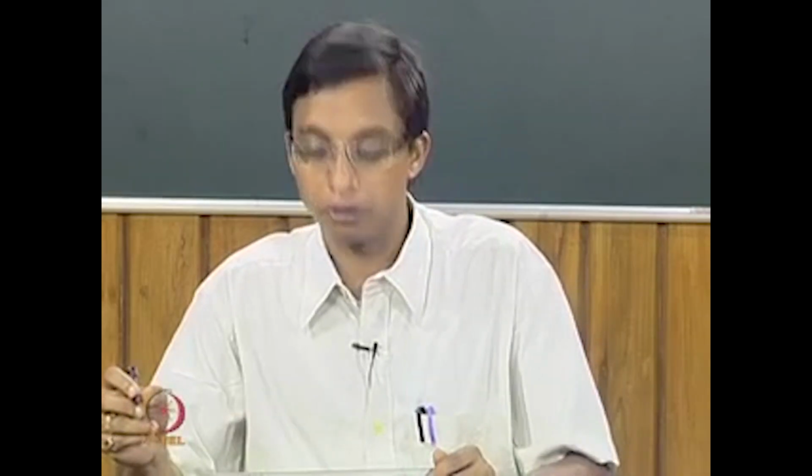I am just showing you how you incorporate the sequent depth ratio in the above efficiency relationship E2 by E1, and correspondingly you will get all the terms in that ratio in Froude number quantities. So, the jump efficiency ratio can be expressed, as I mentioned earlier.